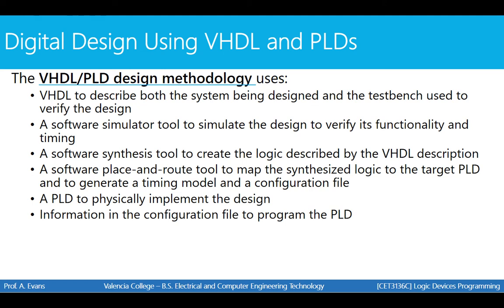So a software simulator tool is often used to simulate your design to verify its functionality and its timing. So today we are going to do the first lab, and we are going to simulate the code that we're going to write before we actually program it onto the PLD. That's called a functional simulation. That simulation is going to help us ensure that our code works the way it is intended before we actually program the PLD.